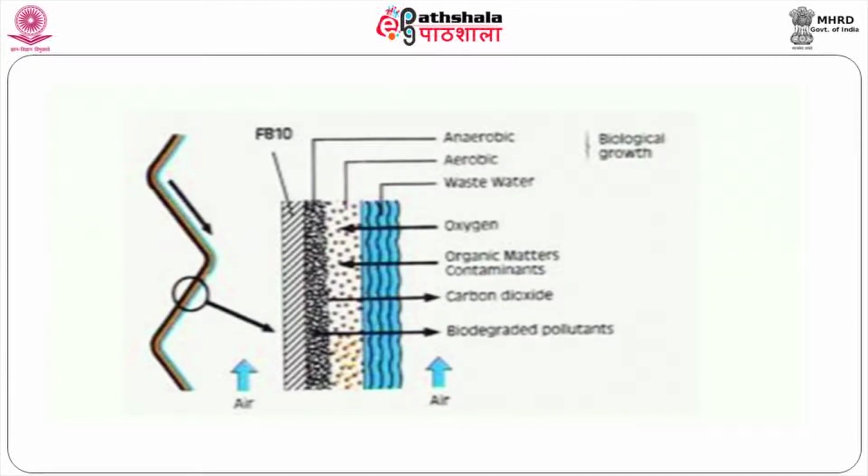So, a trickling filter consists of a solid material. It can be plastic or conventional. The wastewater to be treated is sprinkled on the top surface of the reactor by providing distributor plates. The percolate can be collected from the bottommost surface of the reactor by providing an underdrainage facility at the bed of the reactor. If we sprinkle wastewater on the top surface of the reactor, a thin biological layer will be formed around the surface of the solid material. The mechanism I already pointed out here.